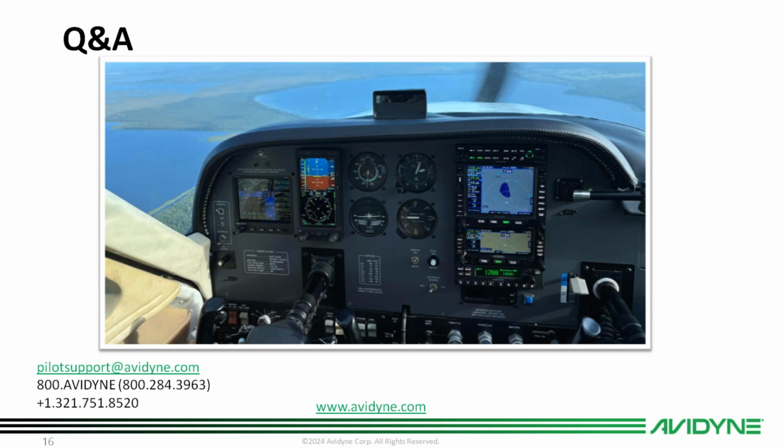Does this work with a GAD 42, 43, 43E to interface with analog autopilots? It does not, no. Actually, sorry, the GAD 42, yeah, I'm sorry, I was thinking of GAD 29. No, yeah, it works with a GAD 42. I'm not sure about the 43 or the 43E, but I know the GAD 29, the regular and the B model, as well as the GAD 42 do work.